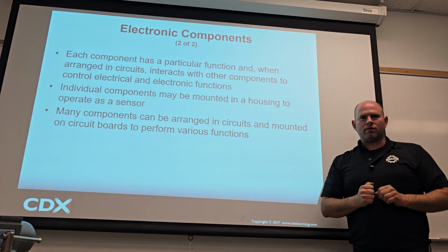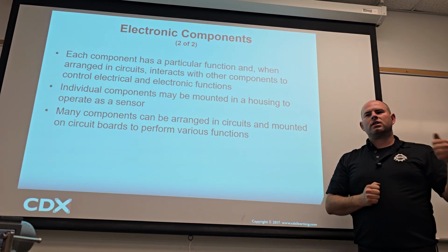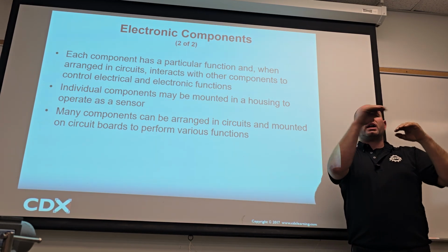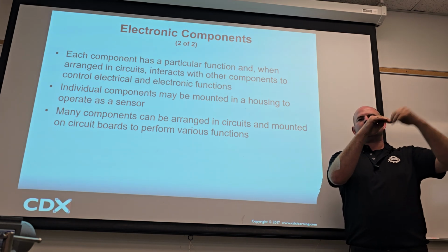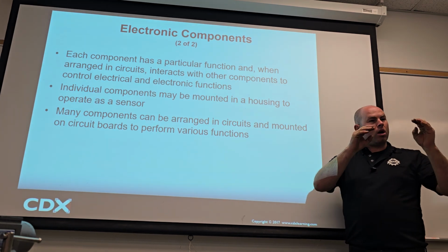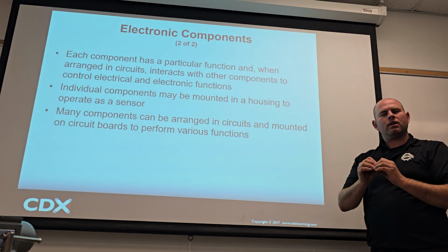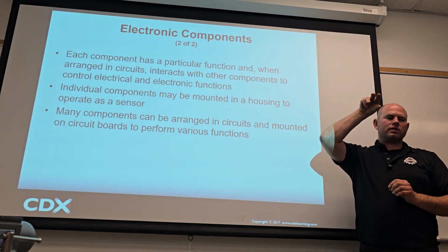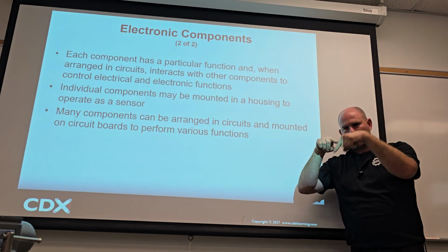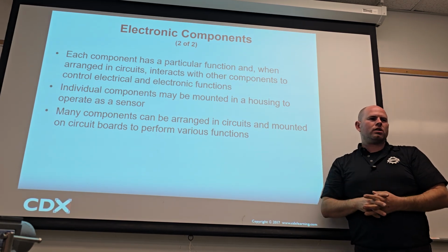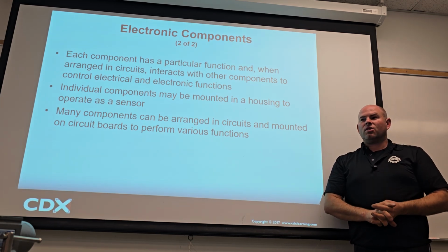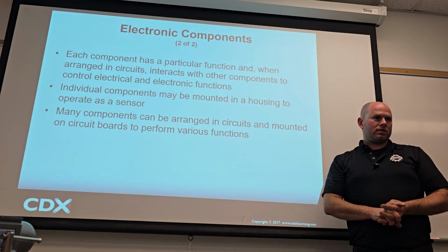So essentially what we need to determine is, is the ECM giving 12 volts or not? No, it's not giving 12 volts. We command the scan tool to give it 12 volts, and the ECM's trying to give it 12 volts, but we're not measuring 12 volts coming out of the ECU. We know the ECU is not doing its job. Makes sense? But on a smaller level, what's actually probably happening is the ECM has to command a transistor on, and that's going to connect the 12 volts to the output where it should go to the harness. And if that transistor is no good, then probably what the ECU really needs is a transistor, but we don't do that.